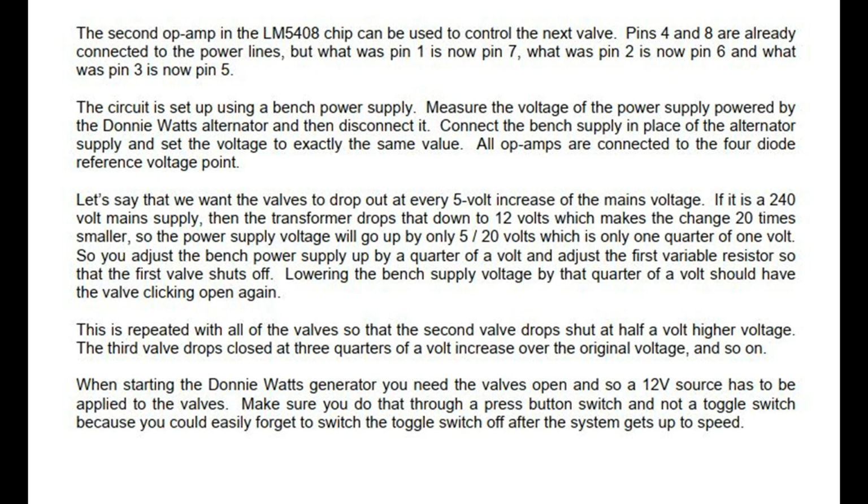The second op-amp in the LM358 chip can be used to control the next valve. Pins 4 and 8 are already connected to the power lines, but what was pin 1 is now pin 7, what was pin 2 is now pin 6, and what was pin 3 is now pin 5.